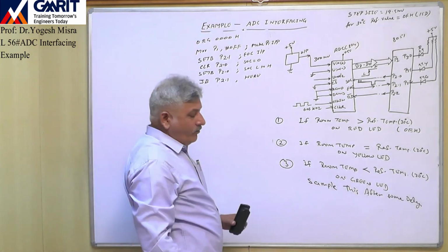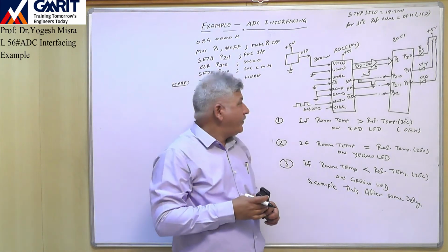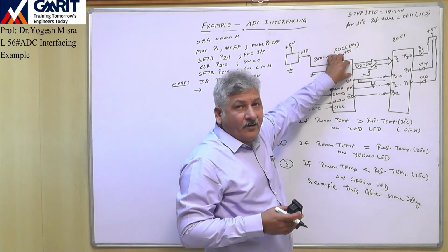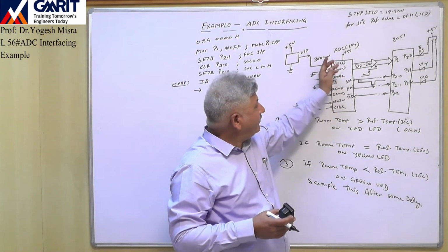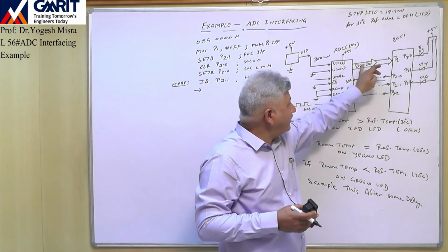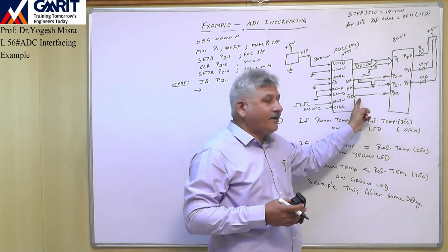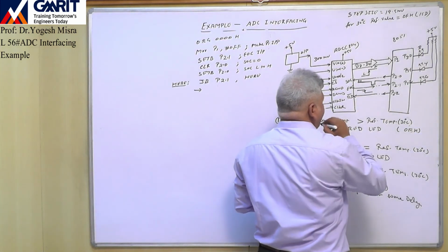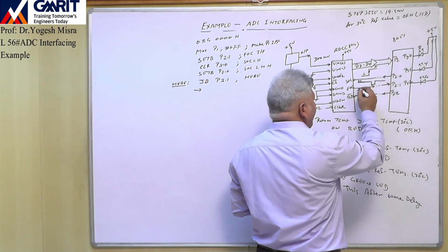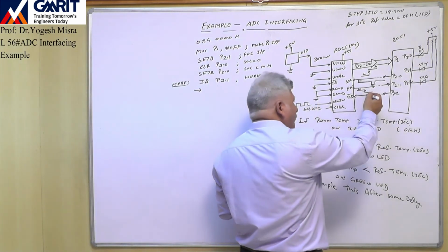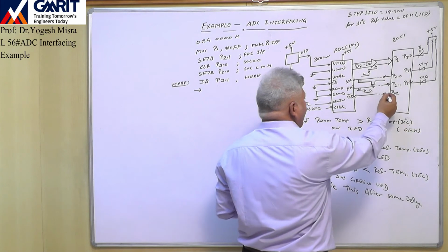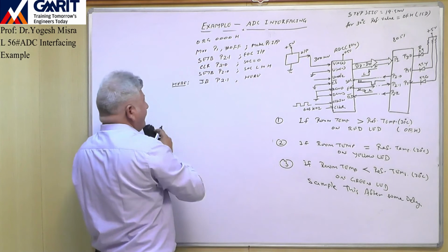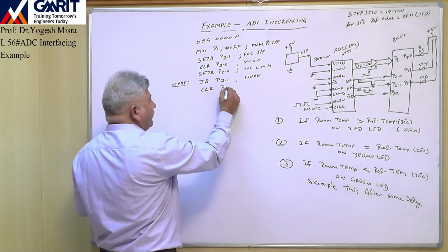So we are here now, we have to read the value of this ADC, right? This value is inside the latch, and that value has to come over to this data line. For that there is a read bar. So here we have to generate a high to low pulse, right? This is an output pin, by default it is high. So simply we have to clear this pin. If you make this pin 0, then a low pulse will be generated. So here we will write CLR P2.2.